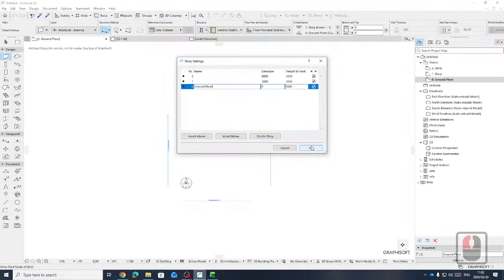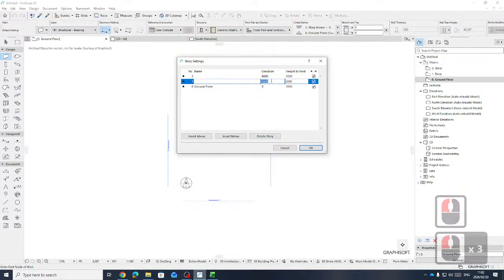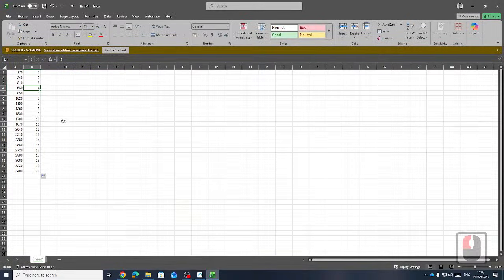Okay, so the first thing I'm going to do is start setting up some floor-to-floor heights. What's nice about ArchiCAD, which is different to Revit, is you can quickly set up your levels using top of floor to top of floor, and I'm going to make that 340 for this exercise. Okay, so it'll give me enough wriggle room. That'll include a server zone.